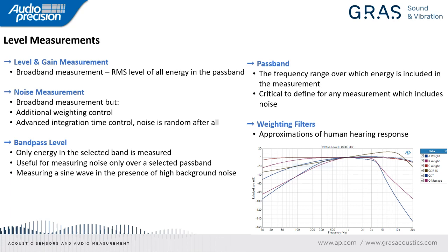So talking about some fundamental measurements, the most fundamental measurement is just measuring the amplitude of an audio signal. Now, even this measurement has some peculiarities we want to understand. And the biggest I want to touch on is what are we measuring? Typically, if you look at something like a multimeter, when you set a multimeter to measure AC level, it just provides a readout. In APX, the equivalent to that is our level and gain measurement.